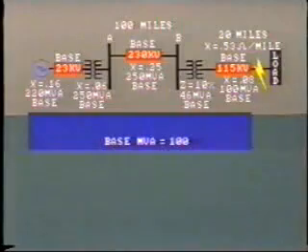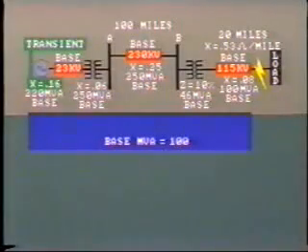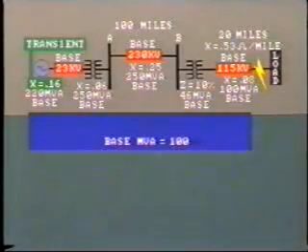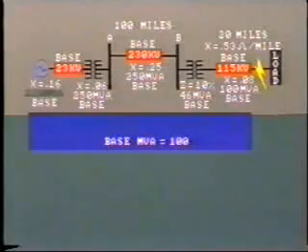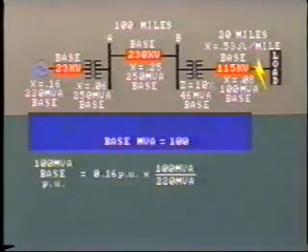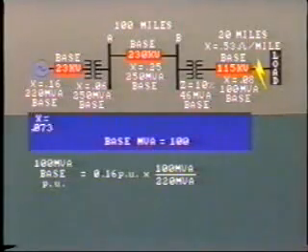Let's do this. The generator transient reactance is given as 0.16 per unit. The term transient refers to the changing conditions which occur initially during a fault. The generator is rated at 220 MVA, so in order to bring the reactance to our common 100 MVA base, we must multiply by 100 and divide by 220. The corrected value is 0.073 per unit.